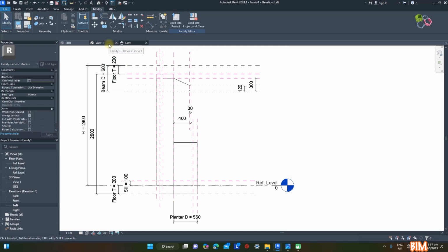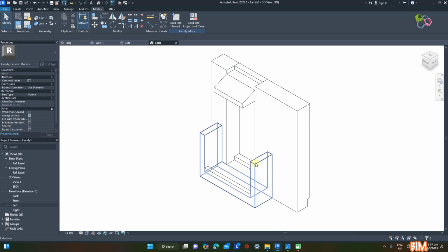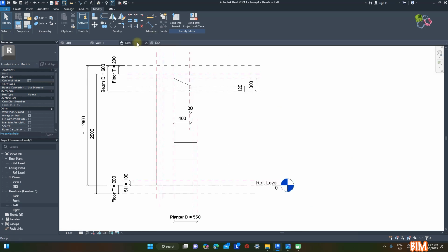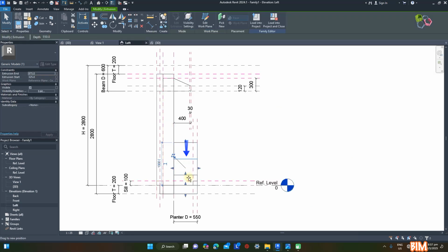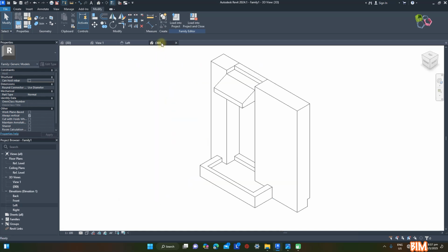In the 3D view, select the component and lower the wall on the right, grabbing the shade handle. A better approach is to work from the south elevation view. Use the Align shortcut, AL, to align the components, or drag down the shade handle. Align it to the sill reference plane, and lock it. Next, drag the left wall, align it to the same reference plane, and lock it. Return to the 3D view and we'll have our planar wall in place.